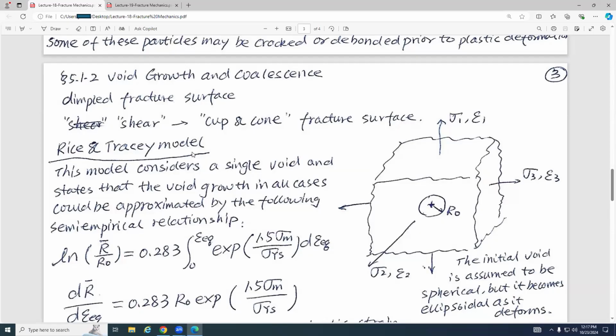It's just a crack. And for the ductile material, we usually have the cup and the cone on the fracture surface. Suppose at the very beginning it is connected together. If we have a loading, here is a cup, and here will be the cone. So this looks like a cup and a cone fracture.